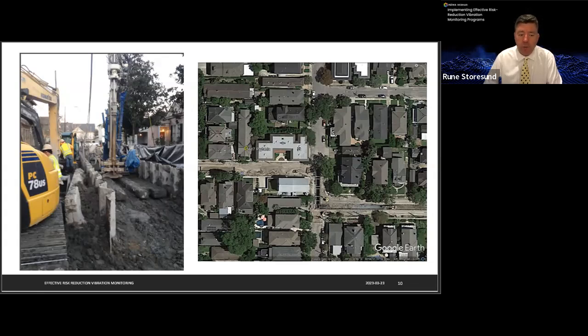This type of work will span many months to even years, depending on the phasing. And in addition, this particular area has a number of older homes, which means it'll be susceptible to new cracking, enlargement of existing cracks, and reactivation of old or hidden cracks that may have been painted over, for example. I would be very deliberate in the development of my construction-induced ground vibration monitoring program for this type of project setting.